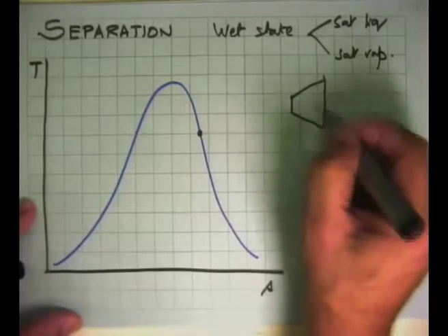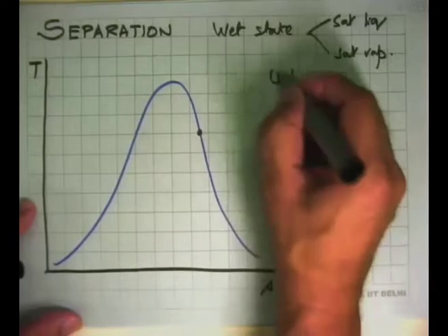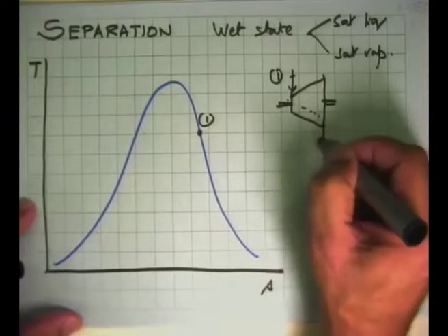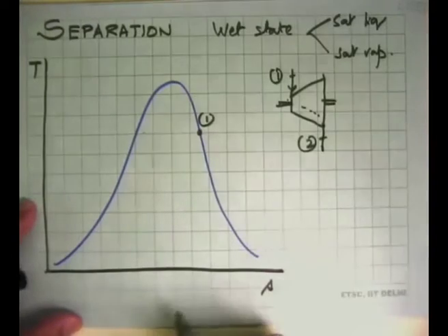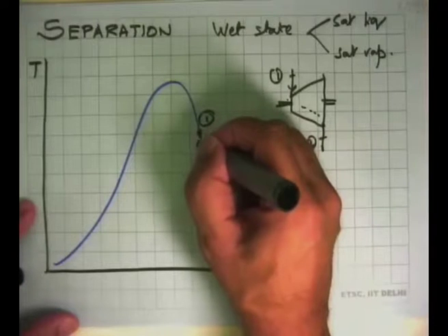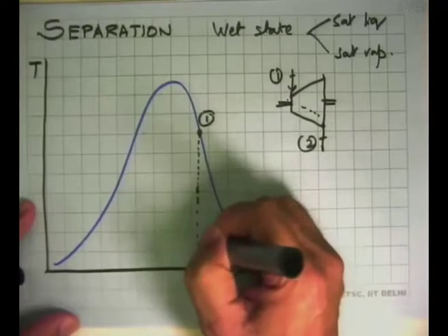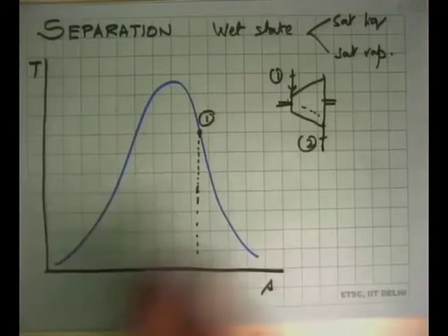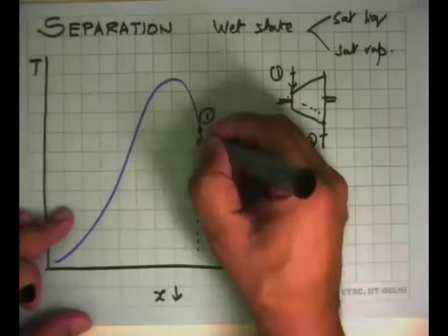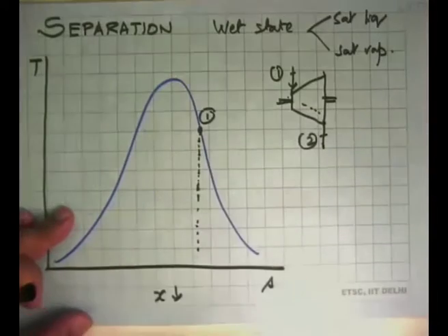So this is the turbine. There is a shaft which is producing power. We have state 1 over there, and we allow the steam to expand in this, and we take it out at state 2. Now what happens here is that because it is dry saturated, the states through which the turbine expands will all be along a line like this. And as you keep going down, the dryness fraction keeps getting worse, from 0.99, 0.98, 0.9, 0.8, 0.7, 0.6, something like that.